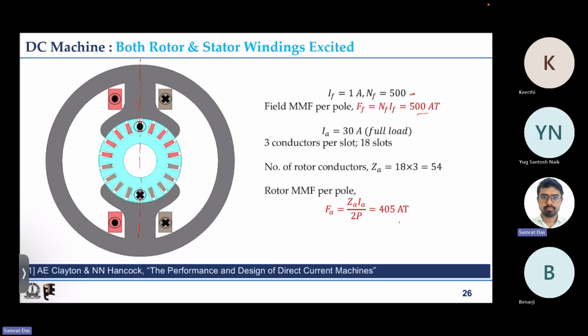On the other hand, for the armature winding, if you look at its axis, you can see that this axis sees the stator pole height, which is a significant number, as the minimum air gap path length. So because of that, the strength of the magnetic flux density is quite low when compared with the flux density due to the field winding excitation.